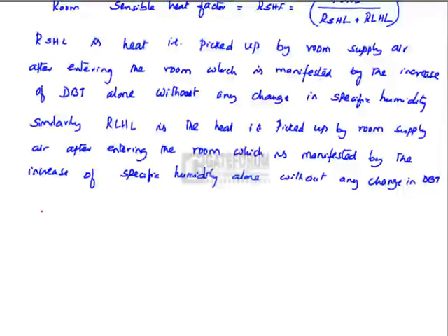So the room latent heat load is a heat load picked up by the room supply air, because of which the humidity of the room supply air alone is increasing without any change in DBT. So this is called room latent heat load.